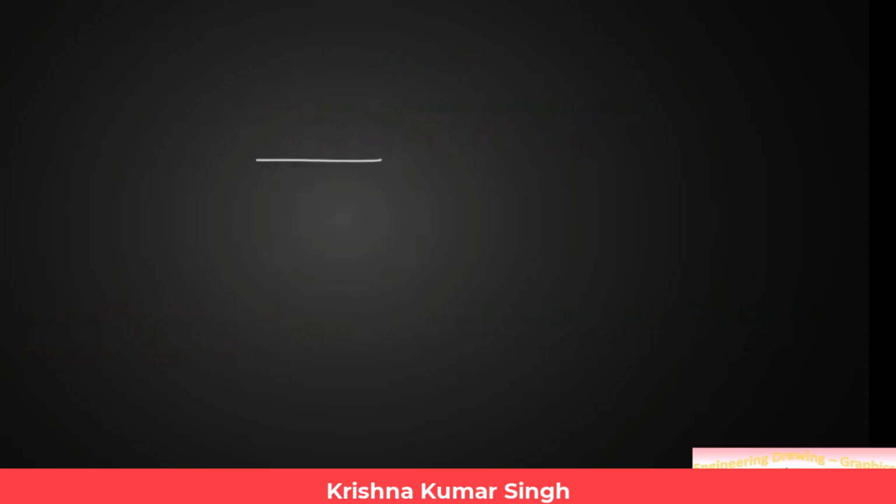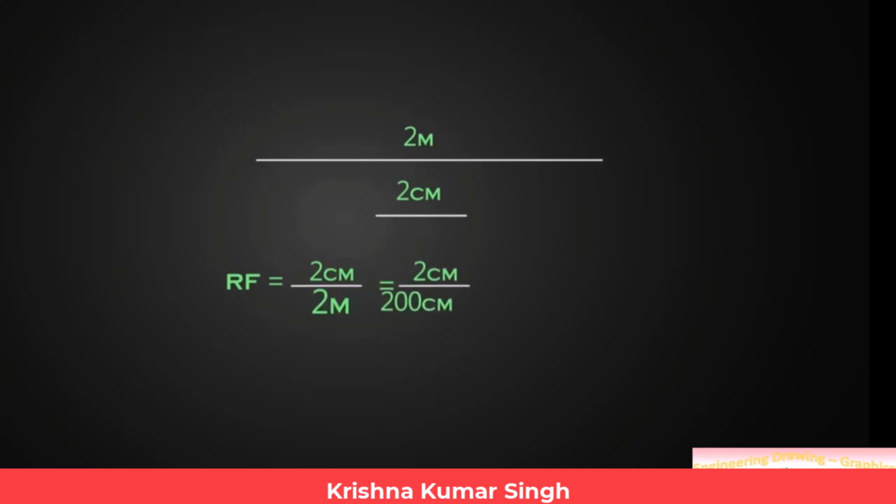For example, if we represent a 2 meters long wire as a 2 centimeters long line, then the representative factor will be the ratio of the length of the wire in drawing to the actual length of the wire, which further equals 2 centimeters by 200 centimeters, which equals 1 by 100.